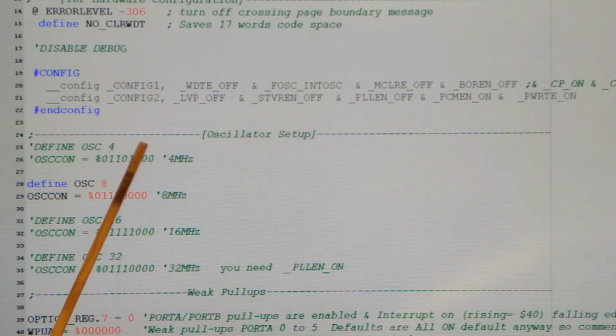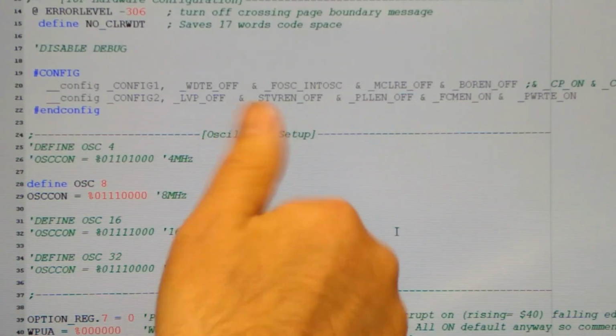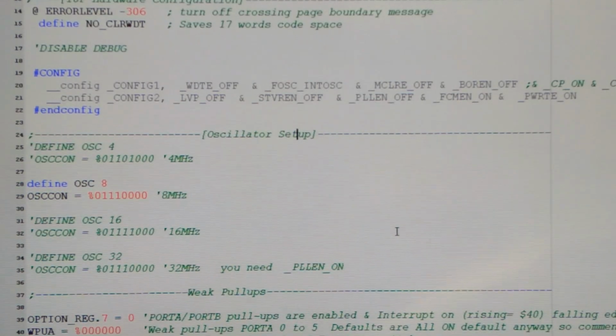At 4, I found that it's a bit too slow, for the reason that I'm running an interrupt to read the rotary encoder, where I set my digits on the LCD screen. I'm setting that, of course, in the microchip. Depending on how quick you are turning the rotary switch, the faster your processor is running, the more you're going to pick up your rotary changes.